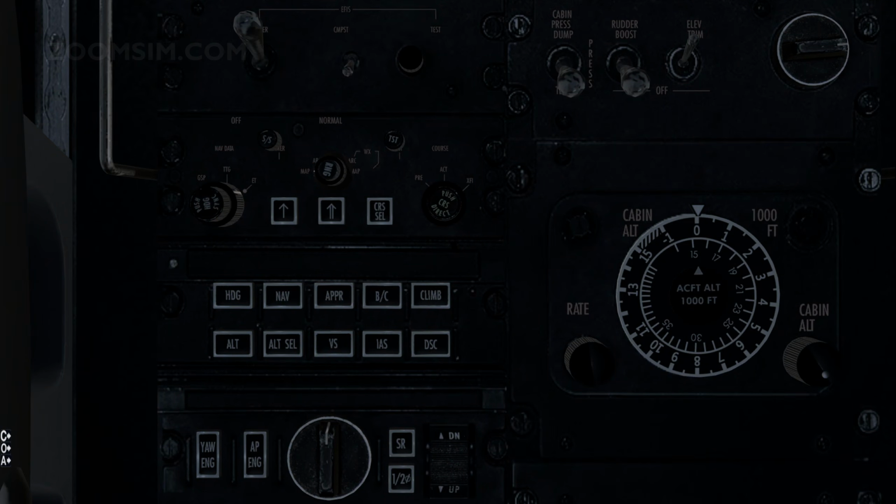Pressurization check set. The pressurization system provides a normal working pressure differential, or PSID, which is the difference in pressures inside and outside the aircraft when flying at altitude. Bleed air from the engine compressor section is used to supply aircraft pressurization. Engine bleed is mixed with ambient air to form a suitable mixture. The flow control unit and bleed air valve switches control the mixture.